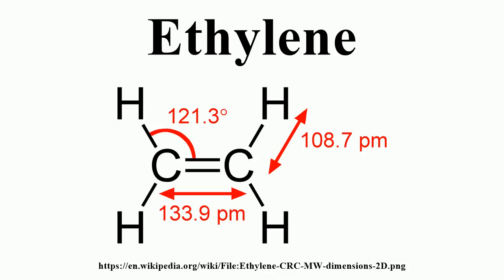The bottom stream from the depropanizer tower is fed to the debutanizer tower. The overhead stream from the debutanizer is all of the C4s that were in the cracked gas stream. The bottom stream from the debutanizer consists of everything in the cracked gas stream that is C5 or heavier.